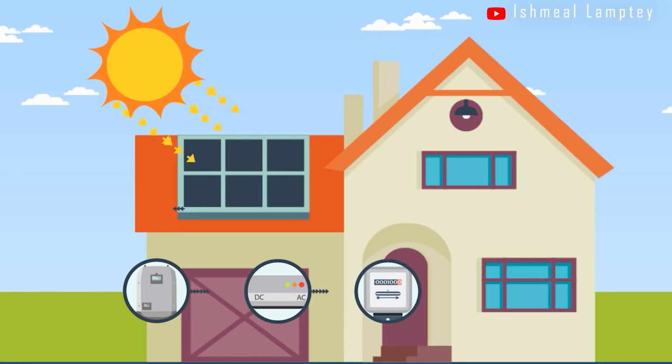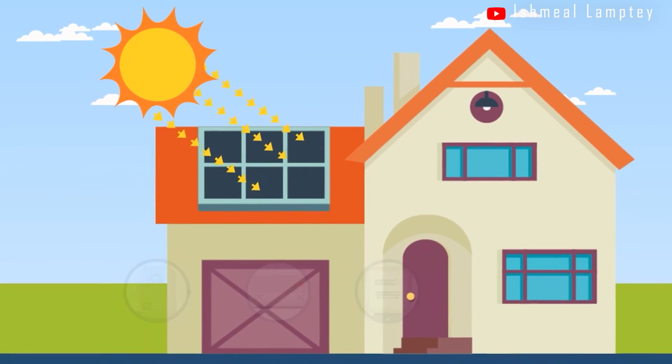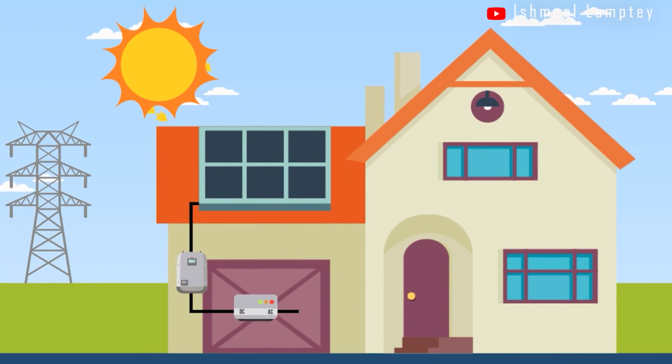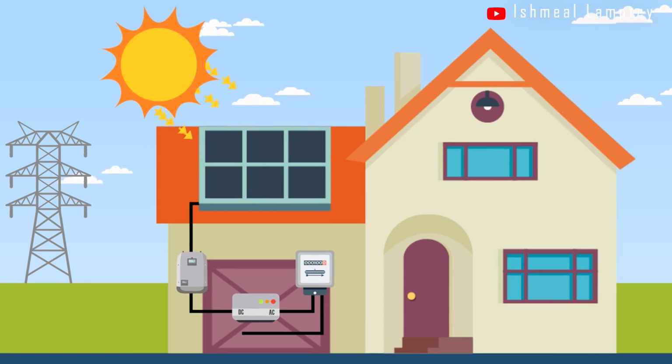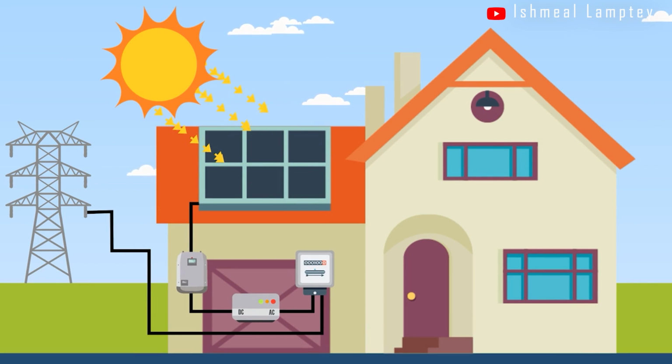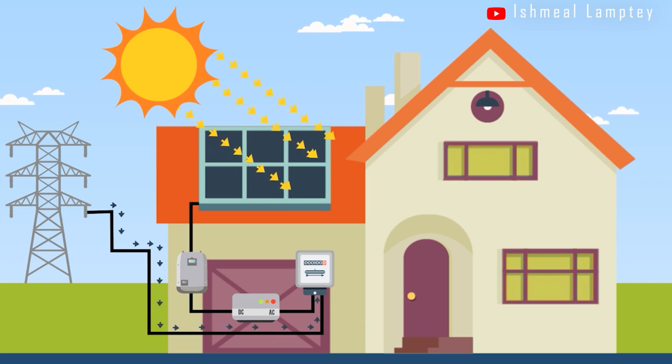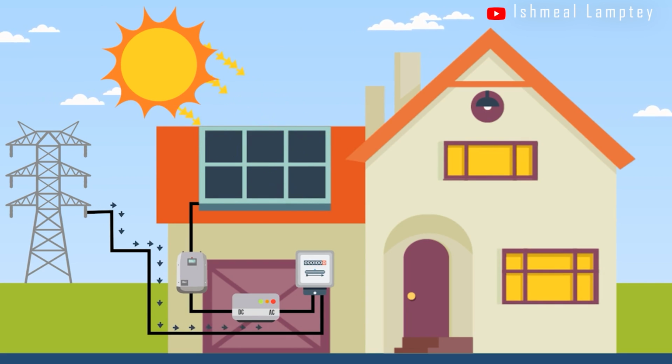Now, the hybrid inverter is designed in such a way that, like I was saying, it takes the grid, it has the PV, it has a battery. So in a situation where there's a power outage, it switches itself automatically. And this is basically how the system is designed. The system can be designed in such a way that when there's a power outage, you won't notice it. It will automatically switch from the grid to whatever is present. So if it's daytime, it'll switch to the panels or the PV. If it's nighttime, it'll automatically switch to the battery. So it doesn't blink or the power doesn't go off. It does this in real time.